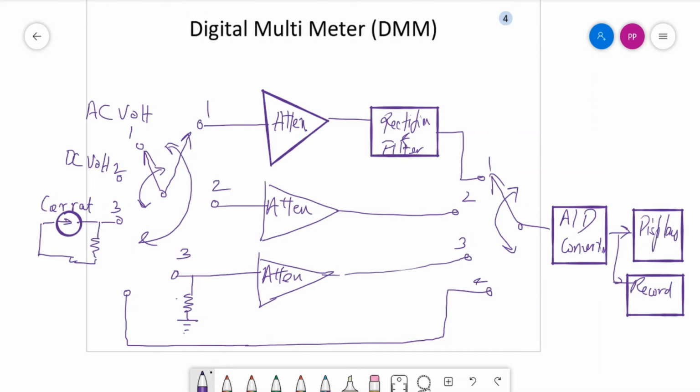This schematic diagram shows a basic digital multimeter circuit. When you switch over S1, S2 and S3, the coupling with the next circuit, that is the middle one through attenuators, if one switch jumps to position 1, the other switch follows it. So accordingly we have the selector switch as you have seen in the digital multimeter. So the individual circuits for AC voltage, DC voltage, current, and similarly other parameters like resistance can also be measured. Even we have measurement options for inductance, capacitance also.